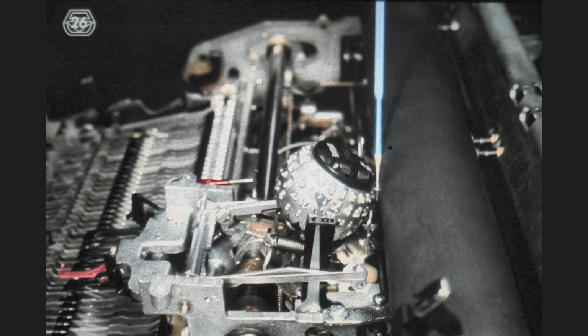We now turn to the adjustment of the maximum power drive position of the element, or the rocker. When the print cam follower is on the highest point of the print cam, the element should be positioned at a distance of only 0.89 millimeters from the platen. The multiple copy control lever should still be in position.